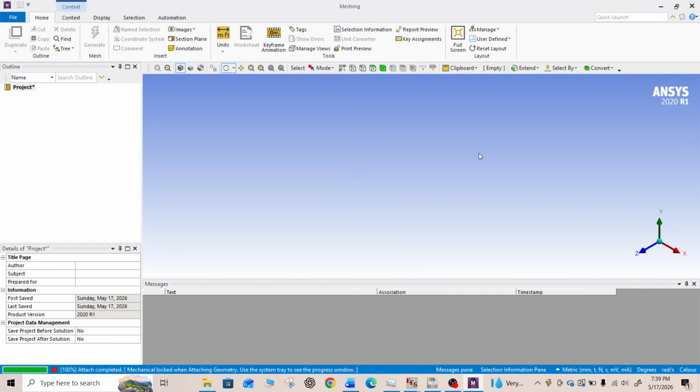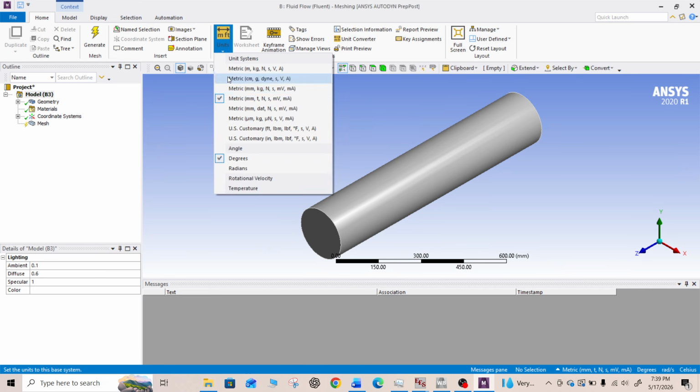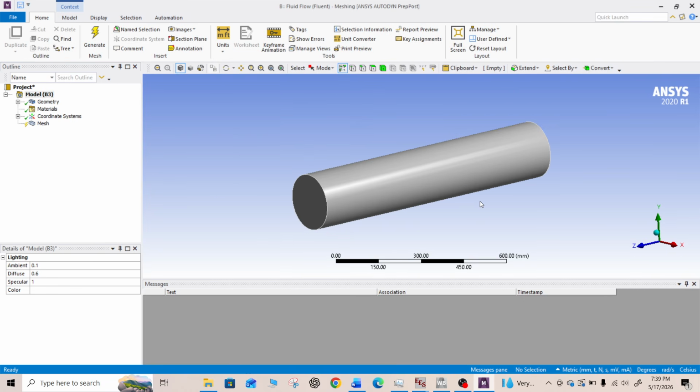Here we're not going to change anything with the mesh, because we're going to keep it as it is. Okay, unit is millimeter. We need to define the sections, because as you see, when you opened it in Ansys Fluent, there was inlet, wall, and outlet. So you have to define it from here. Otherwise, in Ansys Fluent, it cannot determine that.